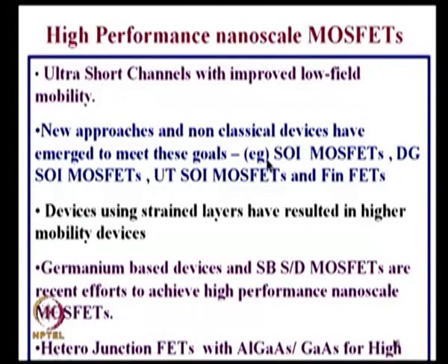So, that is actually using silicon itself, and the trick that you are using in these devices is only controlling the electric fields, controlling the dopants, which is enabled by the SOI device. But now, you can make use of the SOI device. In addition, you introduce strain along the channel. What is meant by strain?